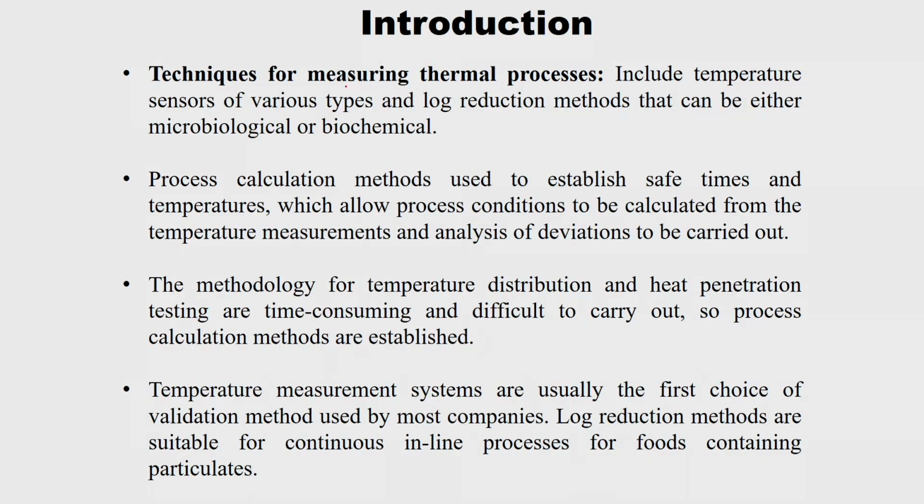The introduction goes like this: the techniques for measuring the thermal process, because I need to do two tests, a temperature distribution test and a heat penetration test, to check the validity of my target microorganism log level. There are two varieties of techniques available. One is direct temperature sensors of various types, maybe thermocouple or data logger system, or sometimes RTD, which is a resistance temperature detector.